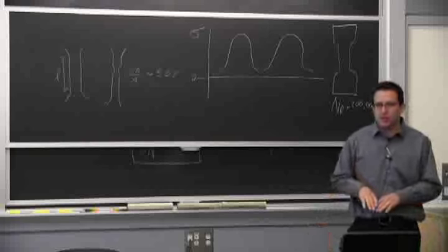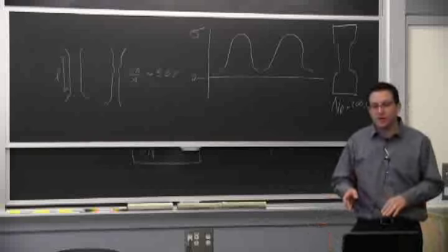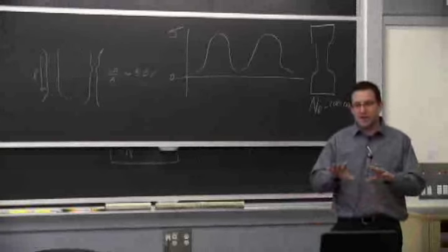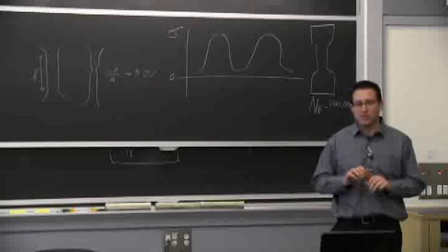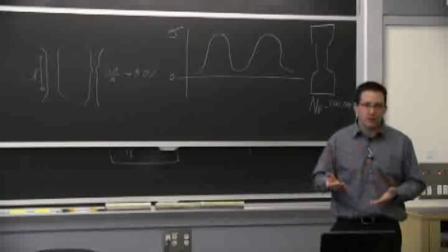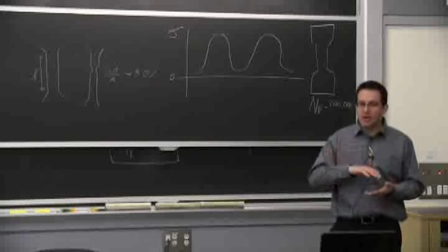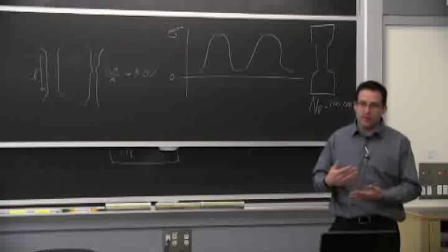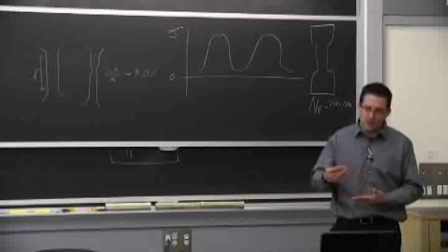Is it going to fluctuate between tension and compression? Is it always going to be compression? If it's always compression, I just want a high yield strength for buckling. I don't have to worry about fatigue. But when I start having a tension component, if it's fluctuating, it could be a different material selection at the end or a different life than if it's tension.